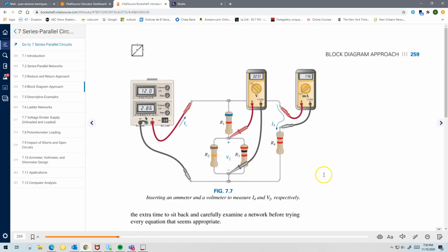And importantly, with this example here, this is the same example, right? And even this late in the semester, I noticed that some of you are still struggling to measure current. Okay, still a struggle, and by this point you should really be comfortable measuring current. And if you're not, take a look at this example, right? This is how you will measure the voltage. Obviously, you don't have to disconnect anything. But to measure the current, you will have to disconnect this point and in its place, put the meter, right?